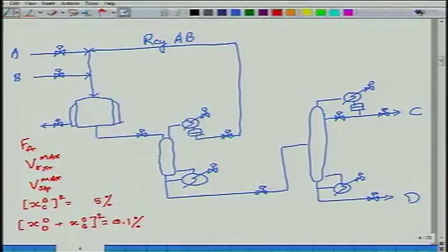Now, I want to draw a control system given that these constraints are active. I have also told you that as I start jacking up the production, because the instruction has come to maximize production, second column boil up becomes max. Yeah, we will do that transition later, but since I know that second column boil up is going to become max.